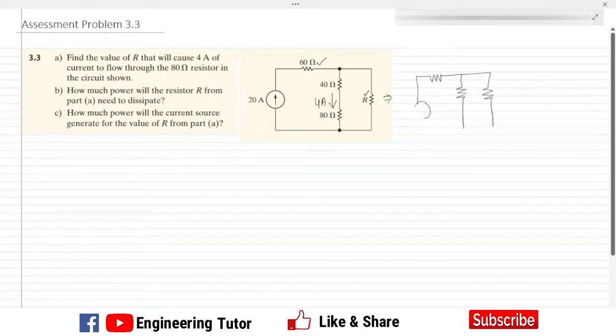okay, so this is our input current source, which is 20 amps. This is 60 ohm. I'm not writing omega here, so if something is written above the resistor, it means it is in ohm. These two resistors are in series, so their equivalent resistance will be 120, and similarly this is R. So we know this value.